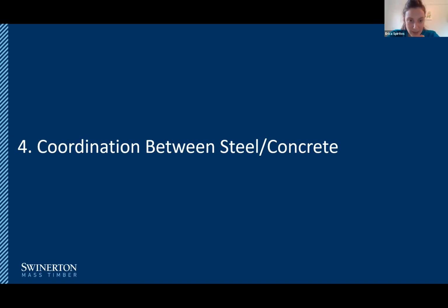Cody, are there special structural connections that accommodate for a 3-hour fire event? That is a great question. And to my knowledge, no, there are not. But that doesn't mean that there couldn't be. Right now, the code only requires 2-hour ratings for the connections. And so that just means that any steel that's in the connection has to be protected for 2 hours so that the fire wouldn't reach the steel in that 2-hour fire event.